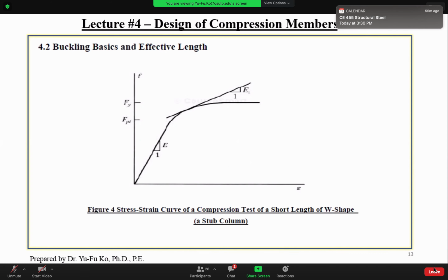Oh, Professor, I did have one question. The Fy in compression value, is that in the steel construction manual? Yeah, it's the same number as the tension. Oh, it's the same number. Okay, I wasn't sure it was the same. No, it's the same because for tension and compression, the yielding is the same, but the curve is a little bit different.